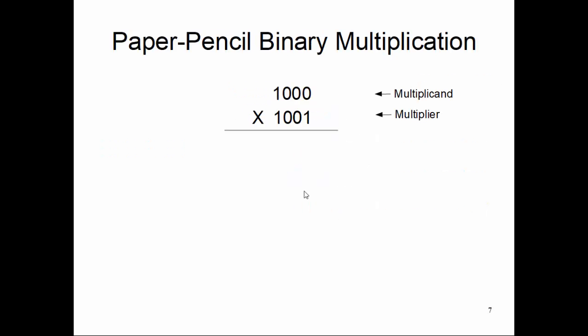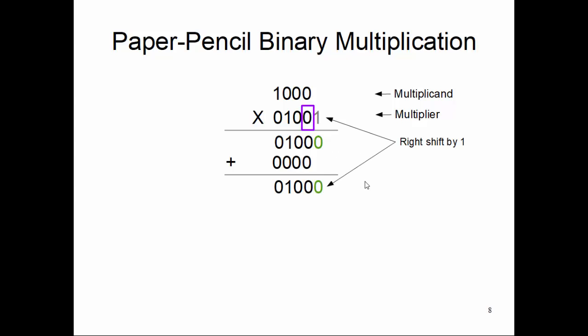So let's apply it here. We start with the first bit of the multiplier, make it this, then right shift both this partial product and the multiplier together, and we keep the first bit shifted out as a finalized bit, represented in green. Then we do the second step, add them as a 4-bit addition, and then right shift both.